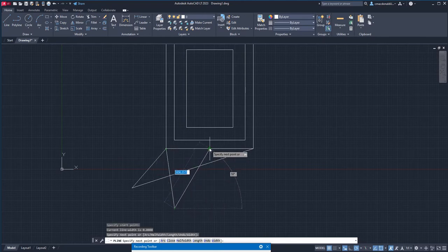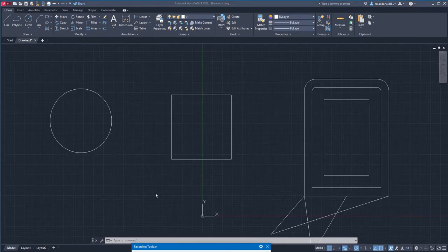And now you can see from the little green indicating shape there, AutoCAD's actually going to snap to that point now. It won't just snap to the endpoint here. It actually knows I want to snap to a midpoint. And there it is. Let's see what happens when I turn a few of these other snaps on.